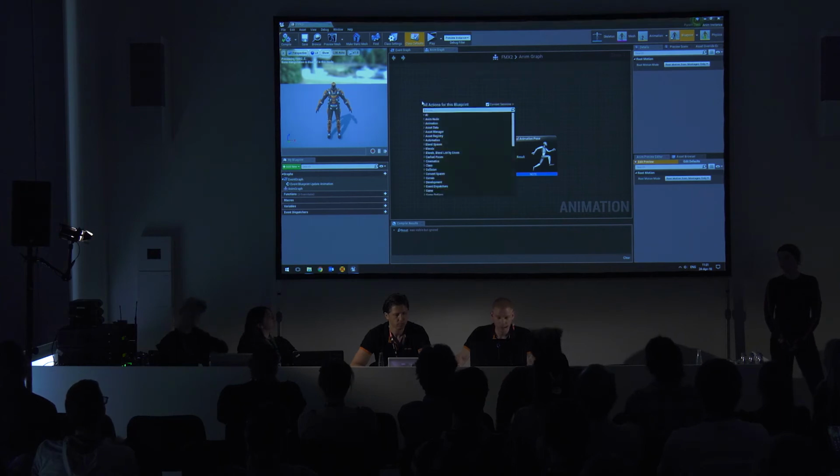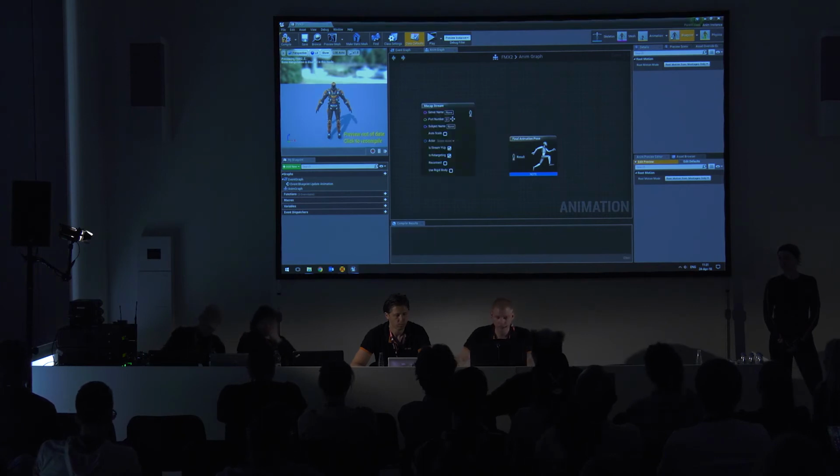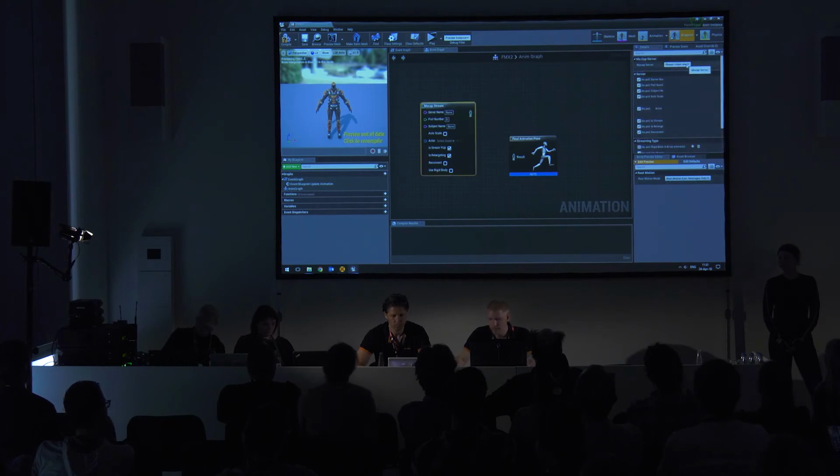So what I need to do is right-click. I can just search for mocap stream, which is from the iKinema live action. I tap this. I need to make sure that the root motion mode is set to, or sorry, where was it? Oh, I need to select it first, of course. I need to set the mocap engine or server to, of course, again, Xsens.